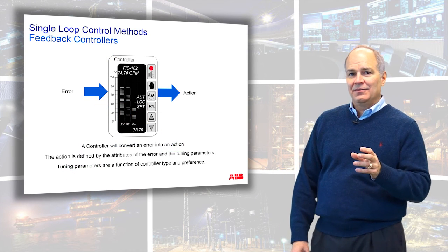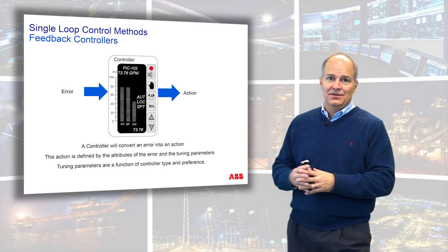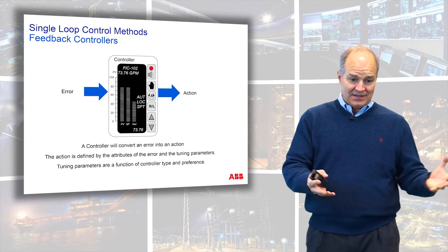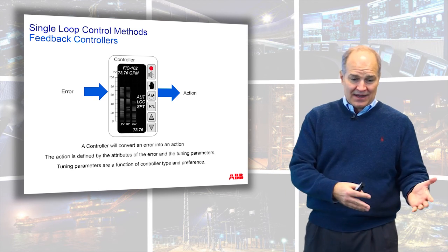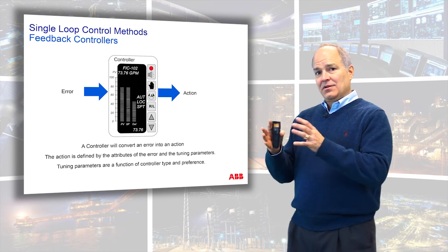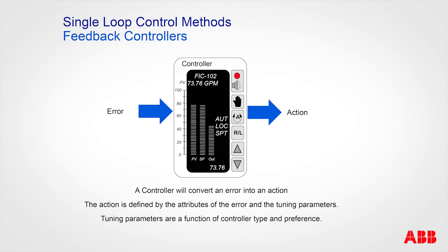When we started, when I hear people say it's just tuning, I'm like, boy, there's a lot to tuning. You have to know the process. You have to be able to identify the process characteristics. You have to understand actuators and instruments and that block diagram. Then when you get to the core, the brain of the controller, it takes an error. We convert the error into an action. And the error is a function of the set point minus the measured value.